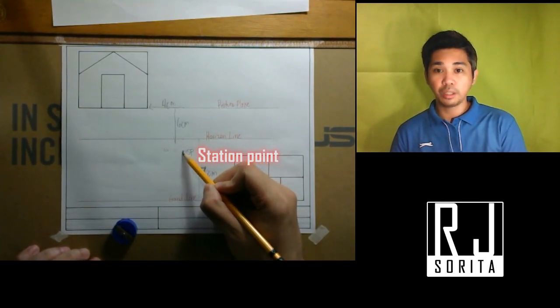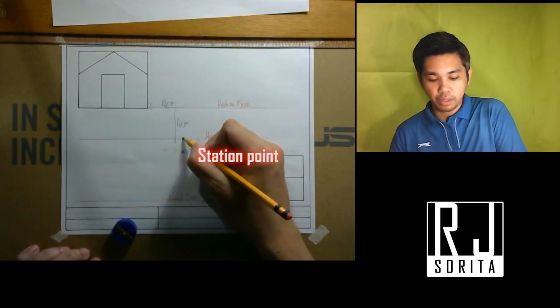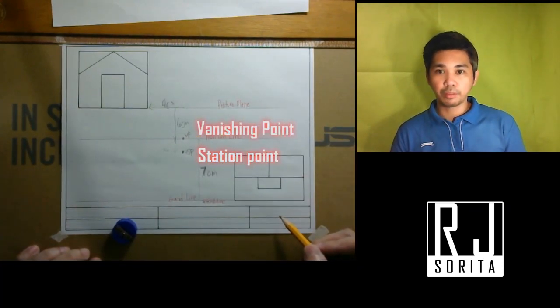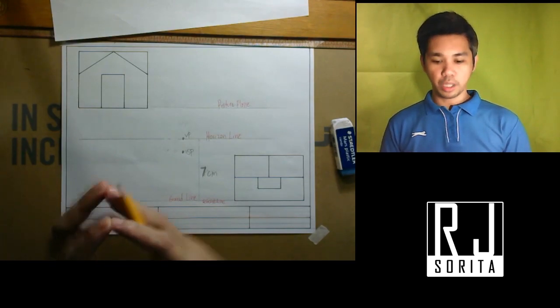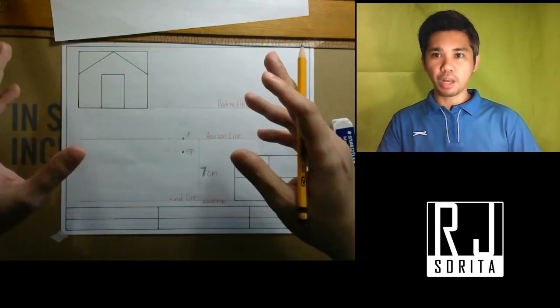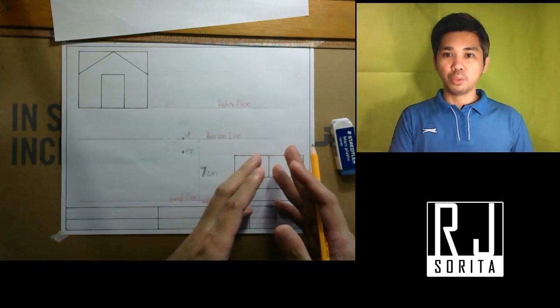Now the vanishing point is always above the station point, and it is located on the horizon line. So this will be our vanishing point. Now we will start creating our three-dimensional object. So what we should do is we have to project all lines from our top view and our front view.